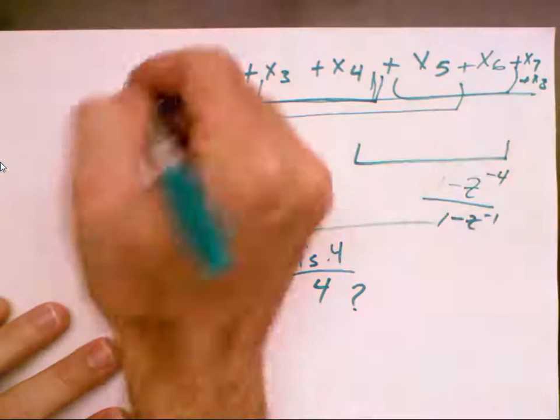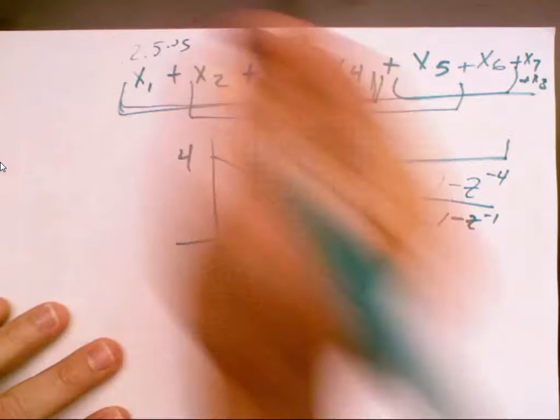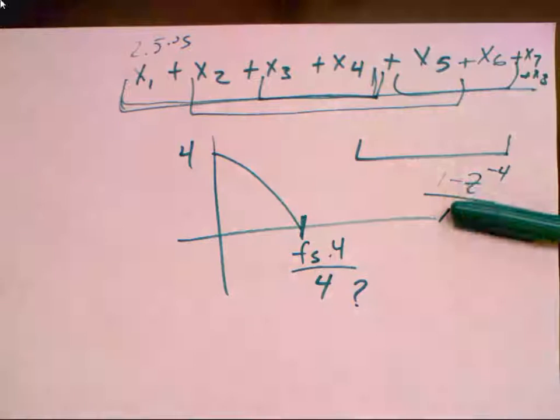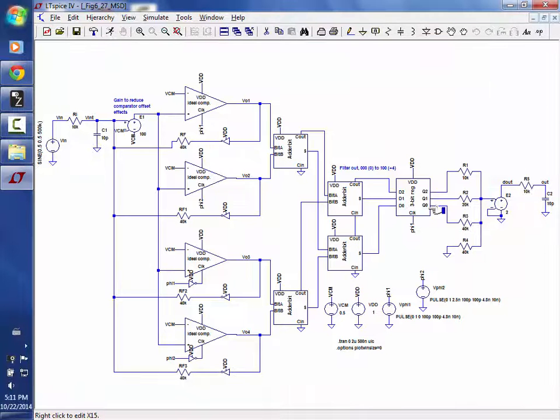Your input rate's coming in every 2.5 nanoseconds, and your output's coming out at 10 nanoseconds because you're clocking it. So the point here is that all this stuff we learned is not useless. You're going to use it. Very practical. Here you see I'm adding them up. That's a filter, and I know what that filter is. But to retime the data, I add this register.